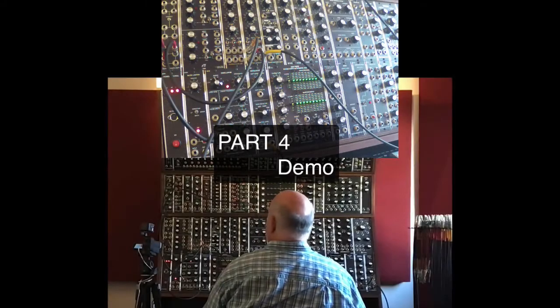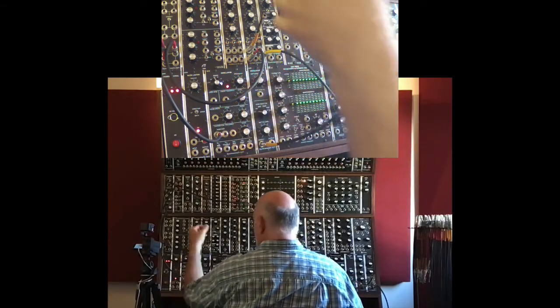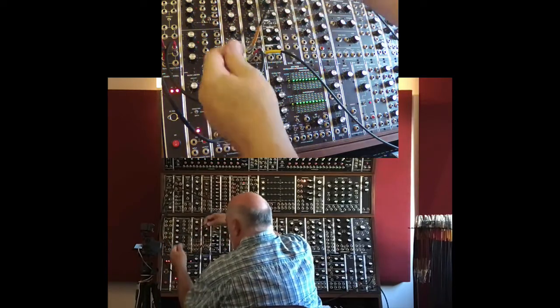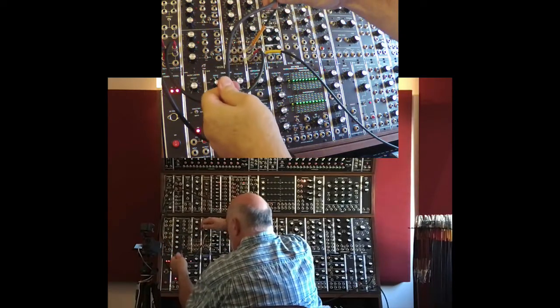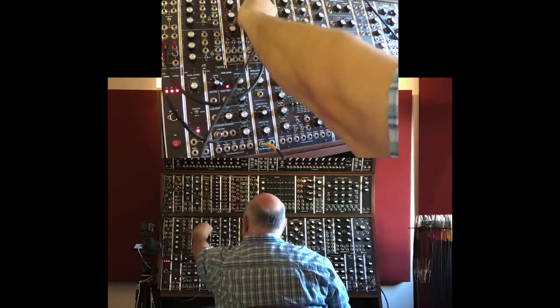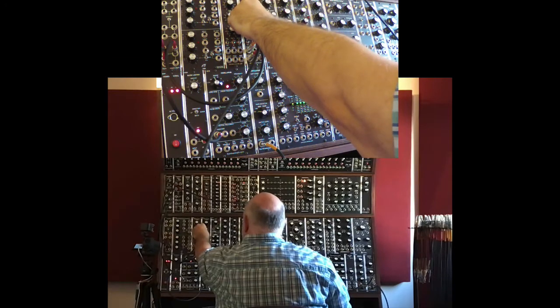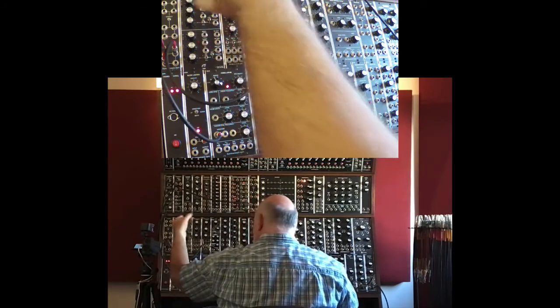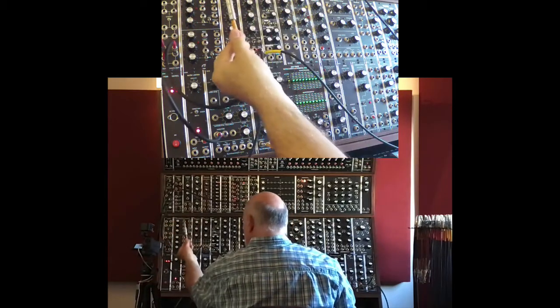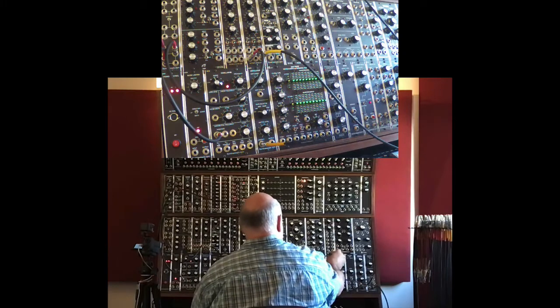For part 4, all you're going to do is take this cable, which is feeding the modulator into the carrier, and you're going to put a VCA in the middle so that instead of your hand doing this, an envelope generator will control the level output of a VCA that this is feeding into. So all you do is you take this and you plug it into VCA input.